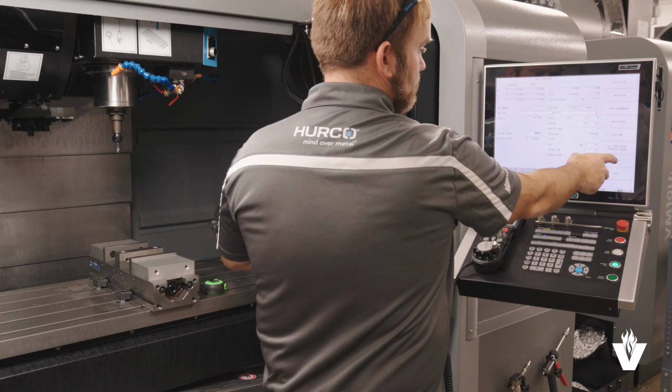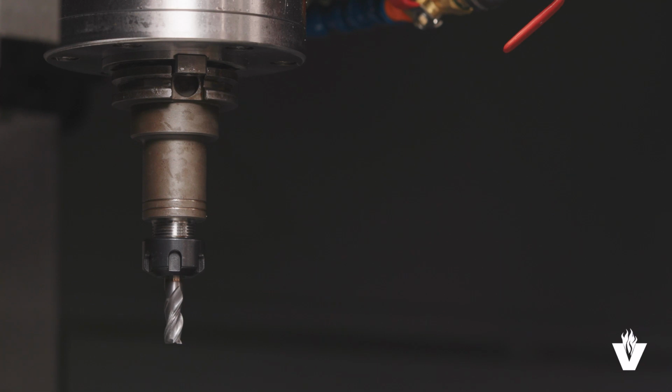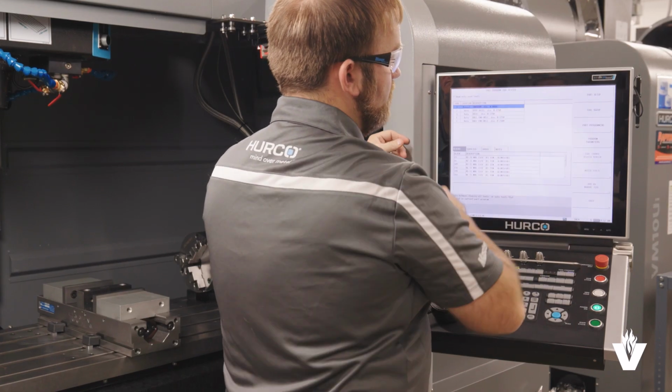In this video, we'll learn how to set up tool lengths on the CNC mill. The purpose for this is to tell the machine the length of each tool and how much is sticking out of the spindle. Now first, we will have to set up our tool in the tool setup page.